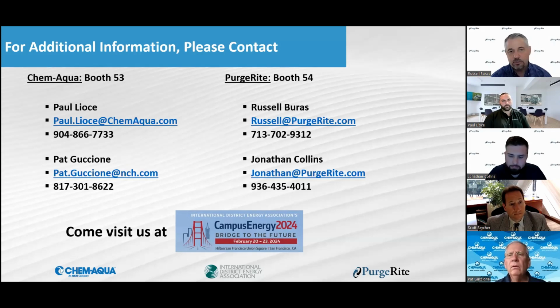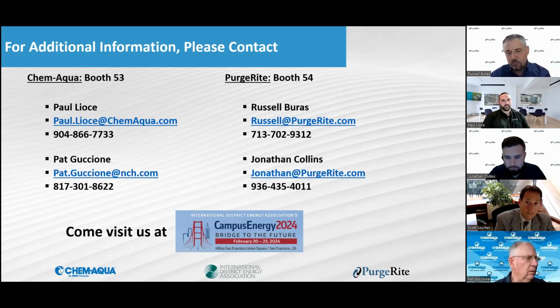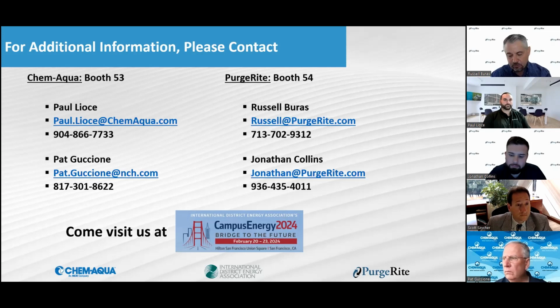Yeah, so what we like to see typically is 5 to 7 feet per second velocity to remove debris, and then we like to tune that down to 3 feet per second throughout, or maybe a little bit less when we're circulating soaps or passivators, etc. We have seen everything from 12 feet per second down to no requirement.